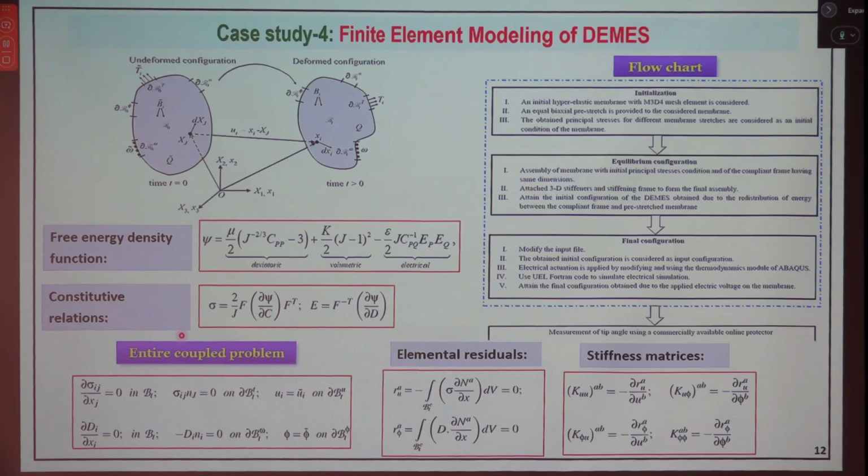As an analytical model, we have considered homogeneous deformation throughout. But in actual practice, this type of structure will undergo inhomogeneous deformation. Inhomogeneous deformation means the tangent modulus is going to change; it's not going to be a constant. So for incorporating that, we have to look towards some numerical tools, and finite element is one of them.